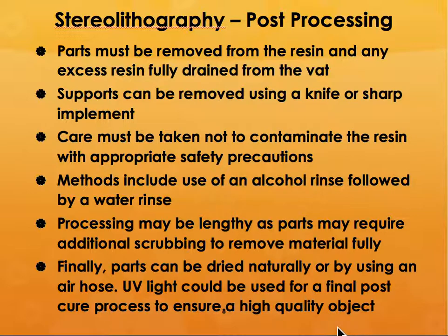And after you make the part, you can use different cleaning techniques, like an alcohol rinse followed by a water rinse. The problem, especially if you have very small layer thicknesses, is that the processing is very, very lengthy. So even a part similar to the one that you saw in the earlier slide can take as much as 15-20 hours and things like that.